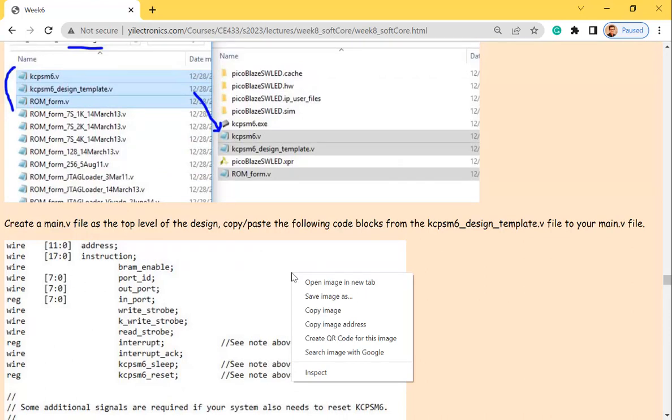I'm just letting you know what's going to happen. Put it in the same folder, run the script. It's going to compile your assembly code into a .v file, a Verilog file. The .v file will have all the machine code converted from assembly, and then you can directly use it as a ROM file like you have been using for your top module in Verilog. You're just adding that rom.v, because that rom.v has all the instructions, the ones and zeros in there. That's how it works. It's the big picture of it.